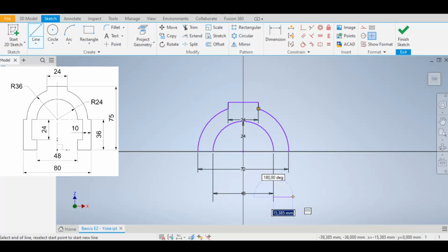to this section, so you can see that we don't have the direct dimension, but I'm going to use the simple math that we can use in Inventor to draw the rest of this. So we know from our center line to the right hand side, we've got 40 millimeters until the end of our drawing, and then we have got 24 millimeters until our first coordinate.